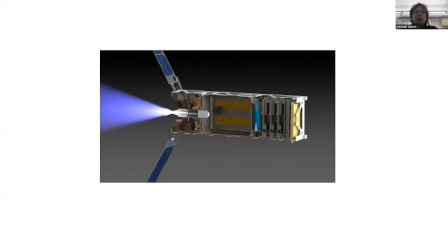But in order to know how your thruster is performing, how you're accelerating, in order to integrate how much you've accelerated, what your before and after velocity is, before and after a thrust or burn, you're again really going to want to rely on the telemetry readout from your onboard linear accelerometers. And from that, you should be able to integrate or do some math and figure out how much you've sped up, what your before and after speed were, and how fast you're going now.